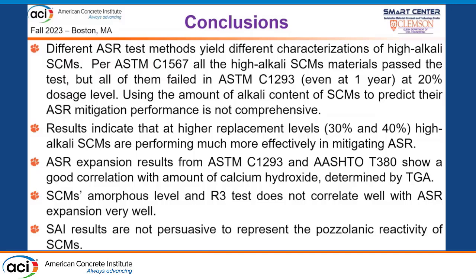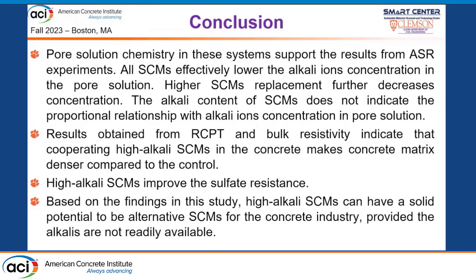Strength activity index is not persuasive for representing the pozzolanic reactivity of SCMs. The pore solution chemistry in this system supports the results from the ASR experimental tests. All SCMs effectively lower the alkali concentration in the pore solution, and higher SCM replacement levels further decrease the concentration.